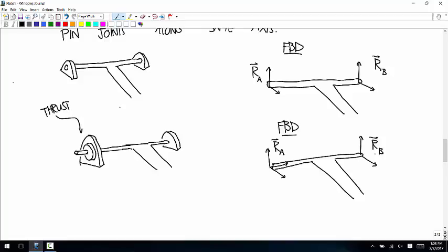So there would actually be no component along the axis if there was no outside force actually making the thrust work, right? That's true. Yep, otherwise it would just, that's right. But that's something you could solve for, so you don't have to think about that ahead of time. When you do problems like this, you just go through the rules of the joints, write down whatever loads are applied by that joint, and then when you put them in the equations, if some end up being zero, you can solve for that. Okay. Any other questions?